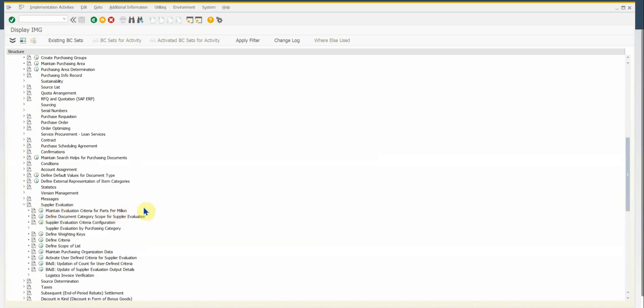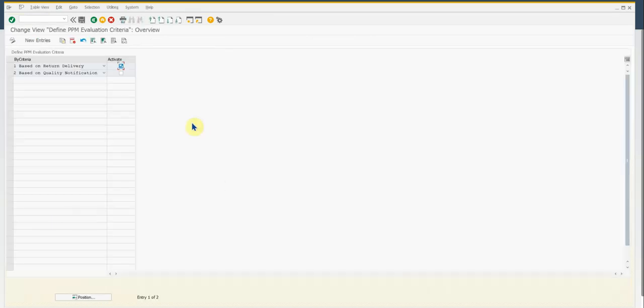If you haven't worked with parts per million before, that is actually where you measure the number of rejected or defective materials that you received from a supplier, but per million. So you do a calculation of X number of defectives received divided by the number actually received times a million. It's just an indicator of the supplier performance.